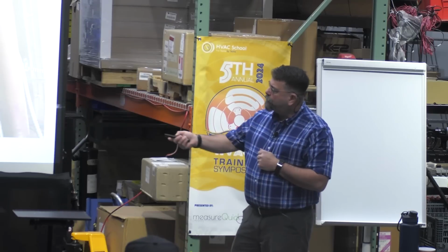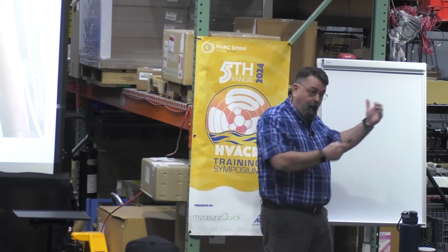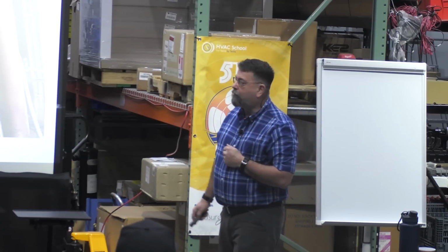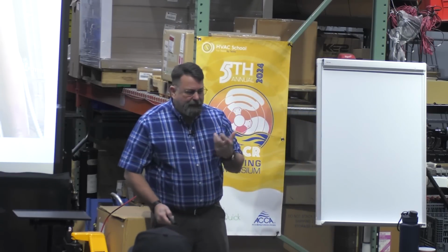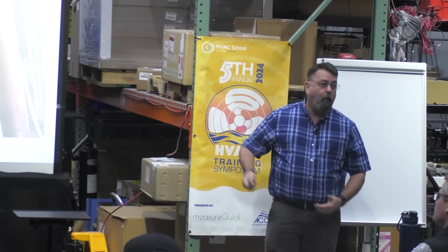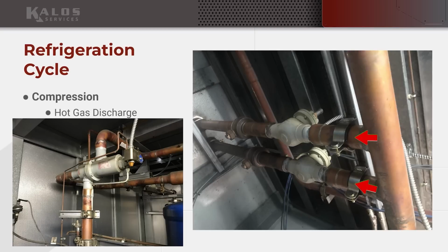Okay, so I've got that going on, and then that reclaimed heat comes back. And the rest of it goes through my condenser, okay? Whatever I didn't reject. Another feature that we see, this set of valves here, this is my hot gas line, that main line where all those compressors, right? I've come out of my oil, I've now come out of my heat reclaim, and you see it splits.